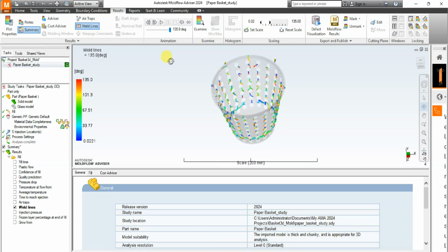One of the things you can check is that the weld lines result helps you to identify the following problems. For instance, structural problems. The part may likely fracture or deform at a weld line, particularly if the weld line is of low quality. The weakness is a more serious problem in areas of the part that are subject to stress. Now, visual defects.